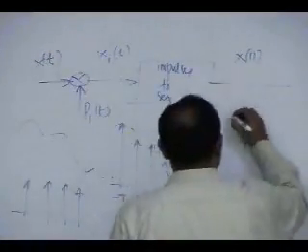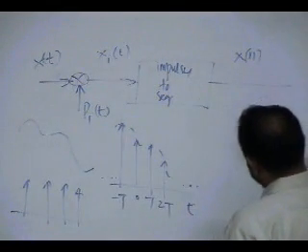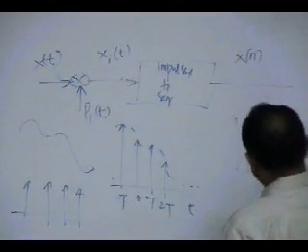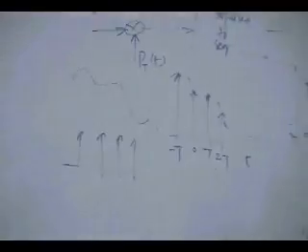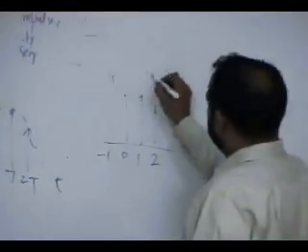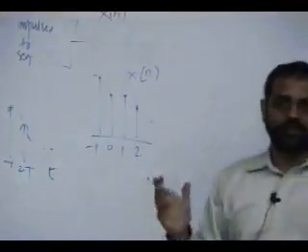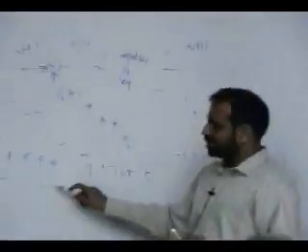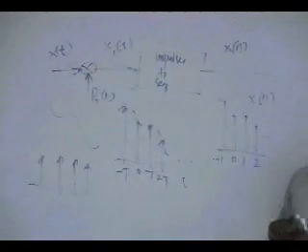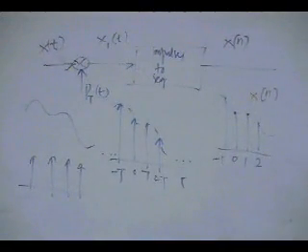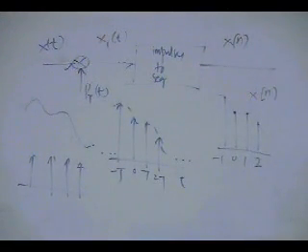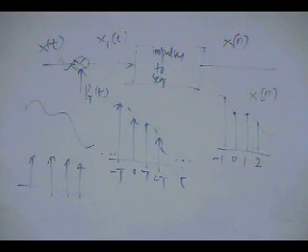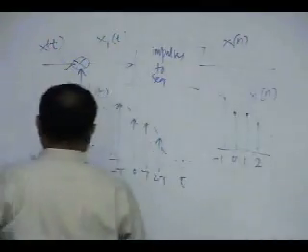And once you get to this point here, you have the same thing but now a digital signal. And these are just indices, and this is x of n. So we need to remember this. These are the steps. In time domain, a signal multiplied by a train of impulses, you get this, then digitize, you get this. This is the mathematical model of the sampling process in time domain, but you really don't get any insight into this. It's not very helpful to understand what is happening. So that's why you take this in frequency domain.